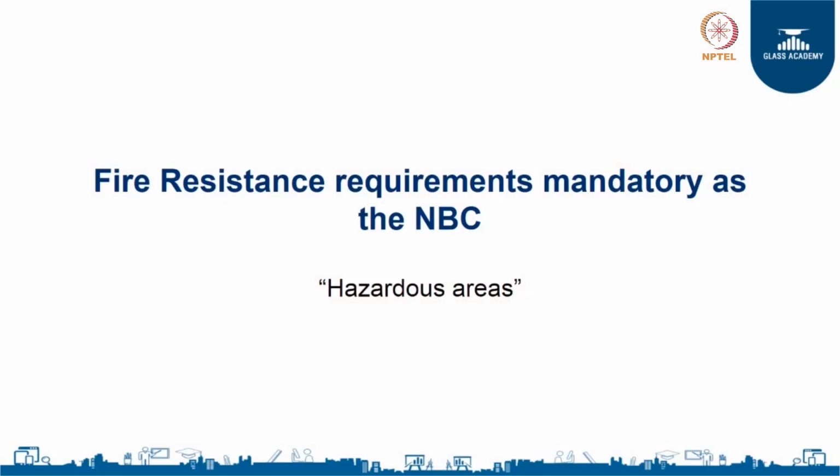Finally, I will take you through the fire resistance requirements in hazardous areas. What qualifies as a hazardous area? Hazardous areas are areas where possibly you can store hazardous chemicals or hazardous materials, or possibly you have something like a boiler room or a fire command center. Such areas in a building are termed hazardous areas. They have been grouped under hazardous areas.